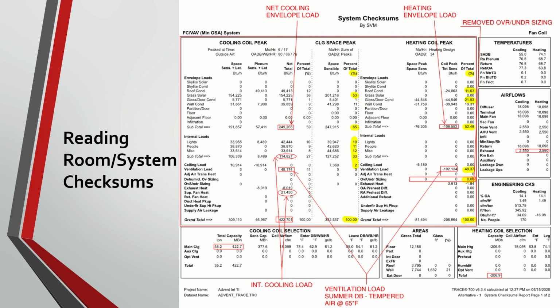So at a system level, it's really good to check the cooling coil selection data to see the total capacity, total BTUs shown, which is in tons or MBH. This will help you size your rooftop equipment.